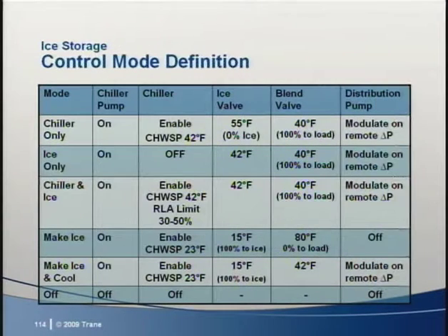The result of this exercise of creating these operational diagrams will be a completed mode table that looks something like this. If transition between modes is important, some designers add intermediate steps to let the control technicians know the proper sequence for a proper transition from one mode to another. This table becomes an important part of the job sequence.